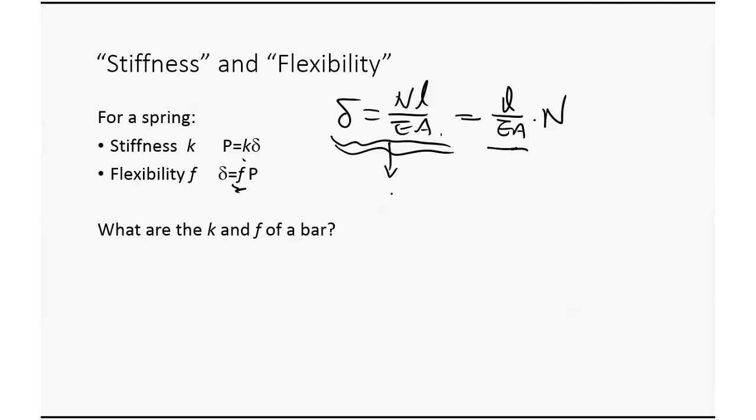Can I write this equation, change this equation to N equals EA over L times delta? Is that true? Yeah, so what's this term? That's the K. So we find the spring constant. Now later on, if I give you a spring, here's the spring, find the spring constant. You just use this 3-parameter calculating.